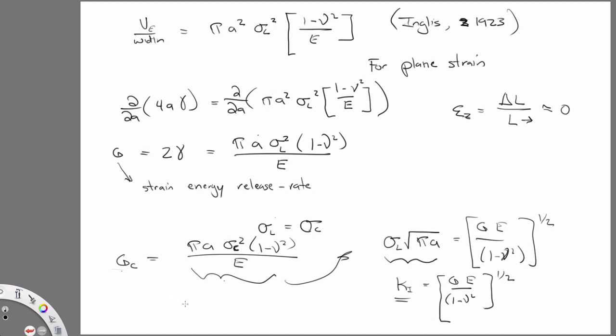determine what the stress field is anywhere near a fracture tip, right? So if we have a fracture, and this is the tip of a crack, we define a coordinate system in terms of polar coordinates from the tip, where this is r and this is theta, okay? And we're interested in the stress field out here in front of the fracture tip. Remember, at the tip of a moving crack, it's basically a moving discontinuity in displacement. You have a displacement jump there.